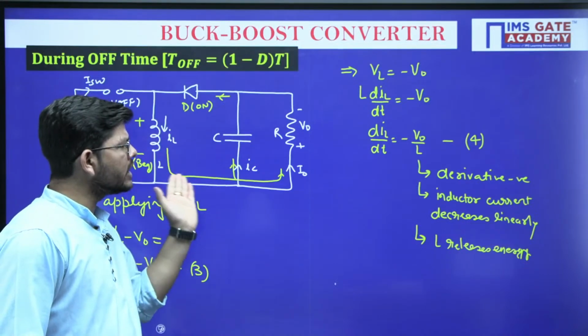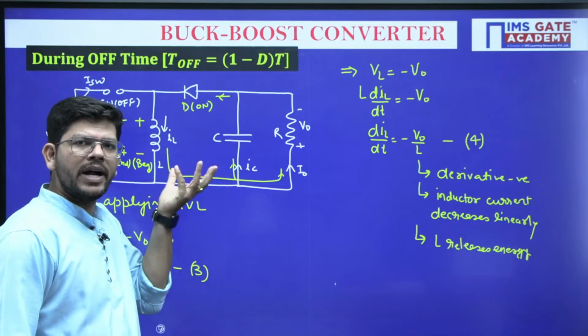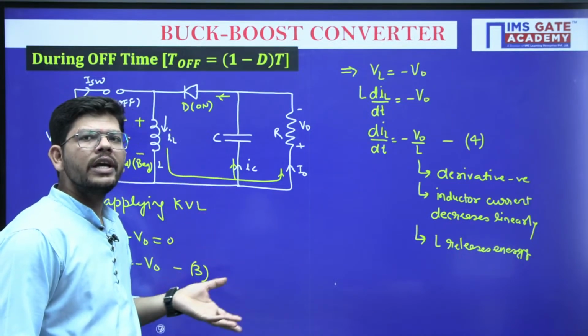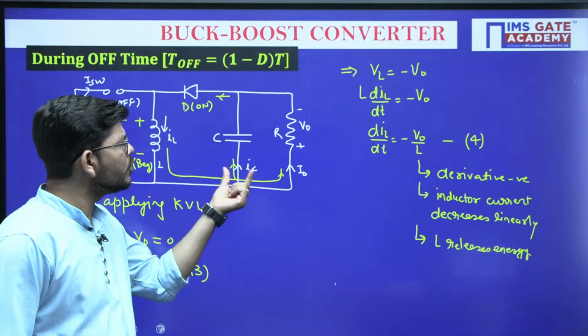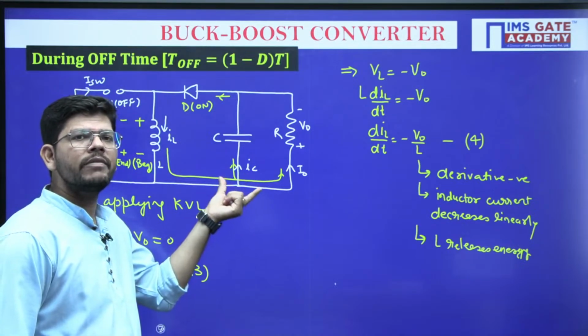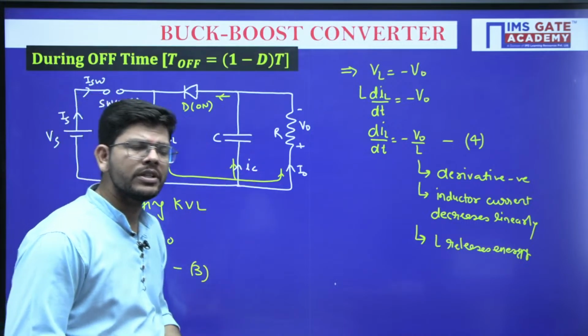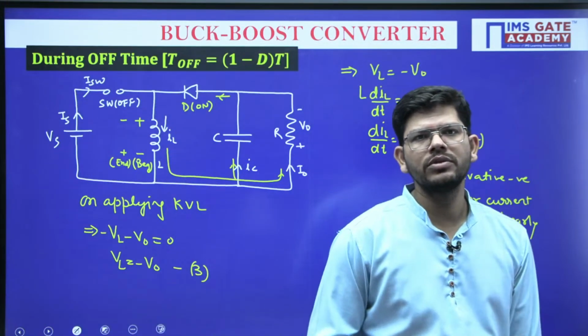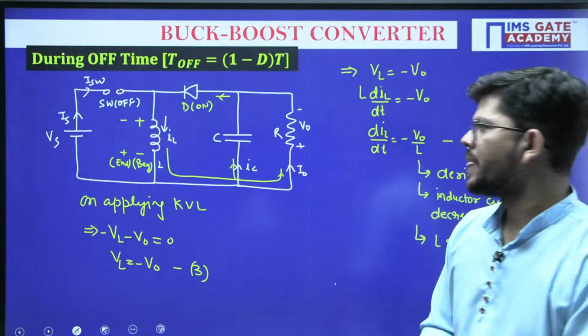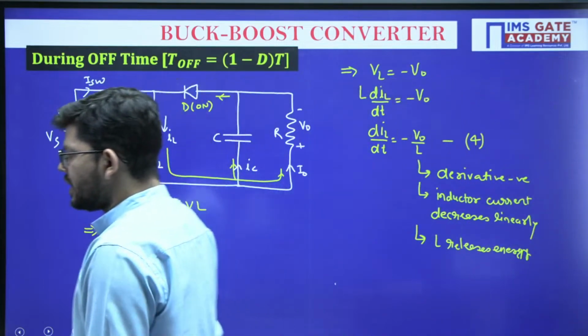So when the inductor current comes, it will take part of that current and use it for charging. So right now in this mode, the off position, the capacitor will be charging. Earlier it was discharging, now it will be charging. So this is how the circuit is going to operate.